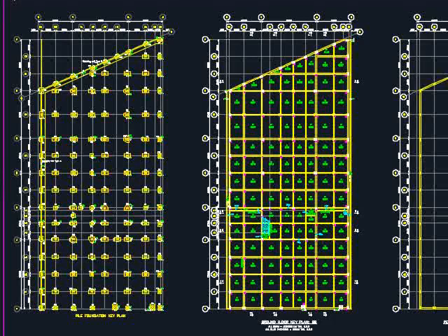In order for you to produce the column schedule, first you will need to refer to the structural key plan. As you know, the columns are connecting different levels of the building, that means they are passing through various levels of the structural key plans.